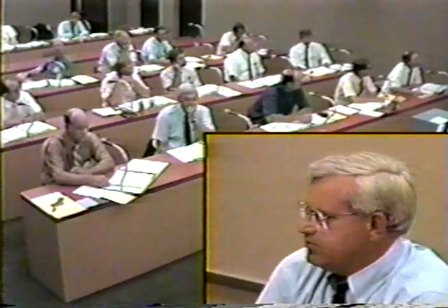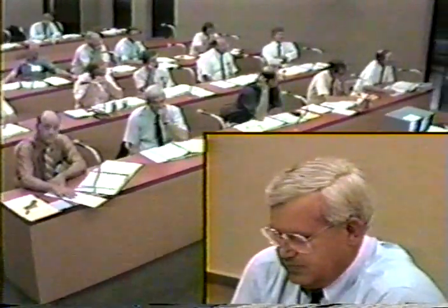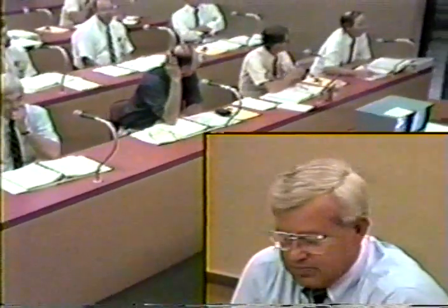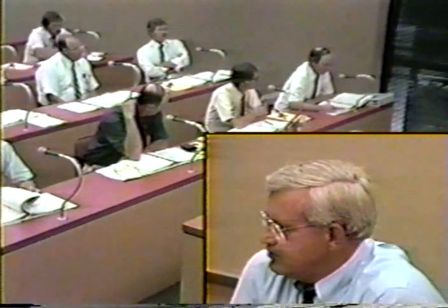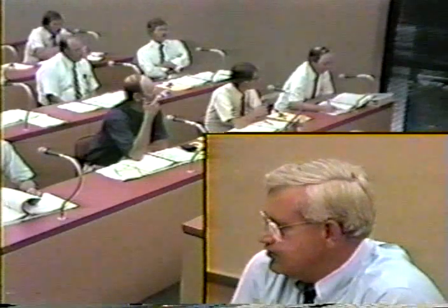Before you go on, Tom, I've got a couple of comments I'd like to go further. Number one, I'd like to talk for a second about berms. You've been talking about them made of rock, and I think that's an excellent idea. One of the reasons we use rock is that the berm will drain, and when the berm drains, that prevents the water table building up and prevents the effective weight of the berm from decreasing. Also prevents slope stability problems of the berm.